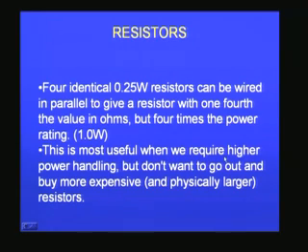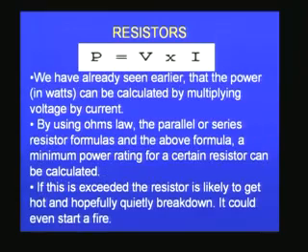This is most useful when we require higher power rating resistors, but we cannot buy them immediately by going over to the shop. So you can use these simple techniques for obtaining larger power rating for your resistors. And we have already discussed power is proportional to voltage into current, and therefore we must make sure when we connect resistors in parallel that the parallel resistors require larger power rating, and therefore carefully choose the combinations so that there is no problem with reference to power rating. If you use a resistor which has got a lower power rating, then the resistor will go bad when you connect them in series due to the heat dissipated, or it could also start a fire.